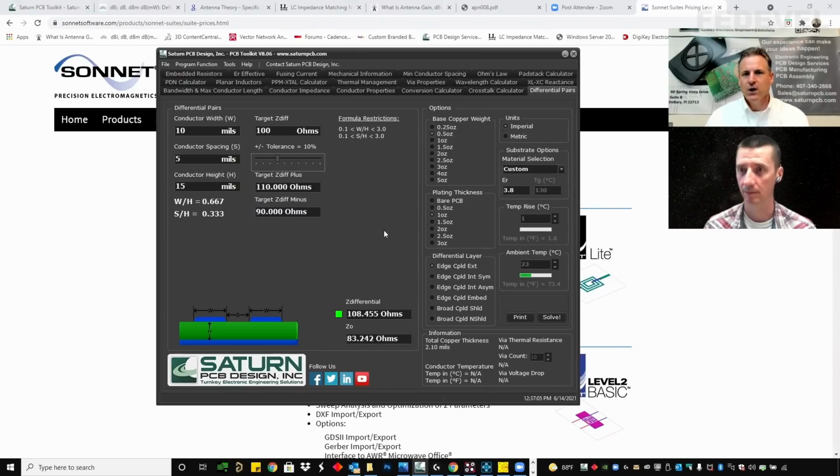accuracy. Again, these are combinational logic formulas. They're not going to be as accurate as EM simulators. And again, the same manufacturing tolerances apply to the differential calculator as they do to the impedance. We were talking about this: you can spend your day trying to get 100 ohm differential impedance, and you'll measure it, and it's not 100 ohms. But the truth is it's going to work.